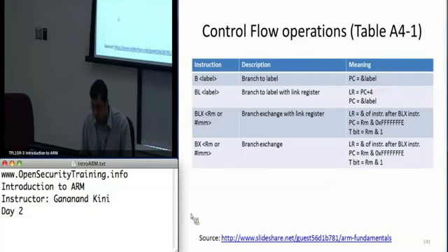Yes, there's my typo. And this should be after BLX. Yes, thank you. So, as Galen pointed out, this should be PC +4. So what it's doing is it's going to look 2 instructions ahead of where the current PC is, add 4 in thumb mode, assign it to the link register, and the PC gets updated with the address of the label, and that causes the branch to occur.